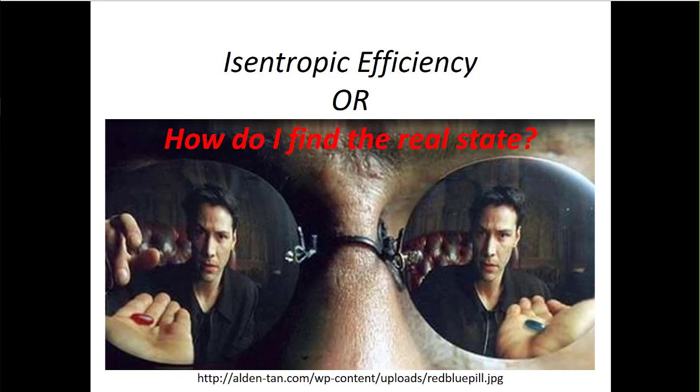Because we talked before about thermal efficiency when we're looking at a whole heat engine, how much of that heat that we put in got turned into power, right? Which is what we're trying to do. Isentropic efficiency is going to only really make sense when we talk about turbines and pumps, because those are the components where when something is isentropic, it's also ideal. So you only really talk about isentropic efficiency for turbines, for pumps, and for compressors.